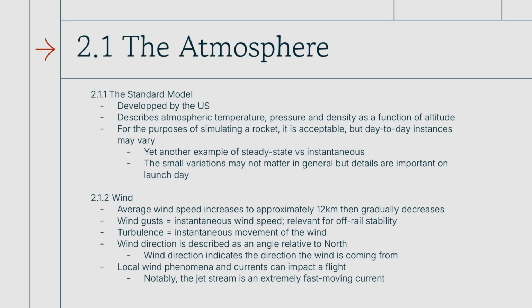Notably, in New Mexico, there's no jet stream, but when we were launching there, it gets super gusty as the day goes by. And we were only able to launch because we analyzed the wind patterns and figured out that there was like a 10-minute window where the winds would die down every day. And we knew exactly when that would happen. And so we were able to time basically all of our setup so that we were ready to launch in that 10-minute window, and then it happened, and we launched, and then the range shut down for the rest of the day. So analyzing weather, pretty underrated, but it can be the difference between launching and not.